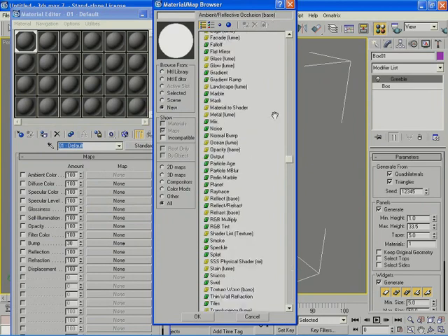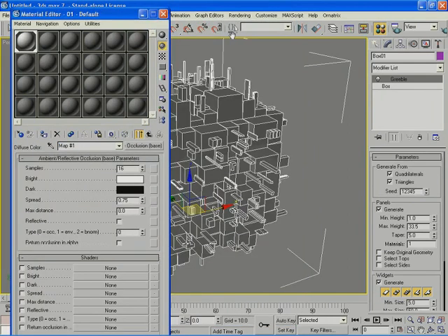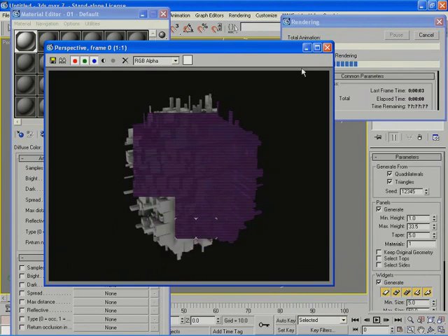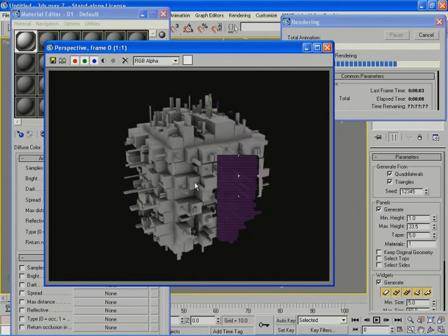So let's see what we get just by adding this map. So if we render now, automatically we're going to have something different happening. We're going to see that wherever I have surfaces close to each other, I'm going to have automatic darkening of my areas. So these shadows that we spent a long time trying to generate with many omni-lights around my scene are here generated for free using the ambient occlusion map. So let's zoom over and see what's happening really between the surfaces.